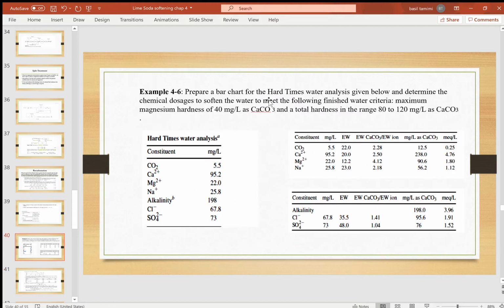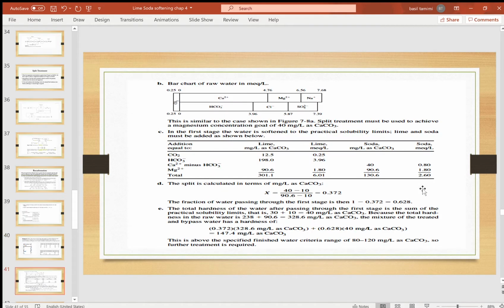the alkalinity and the calcium, let's say we have 238, we have an alkalinity of 198, which means I will have the difference between the two. I will have 40 milligram per liter as CaCO3 of calcium not covered by the natural alkalinity of water, which is this part. So this 40 milligram per liter of calcium not covered with the alkalinity needs an external source of carbonate. That's why we are adding here 40 soda ash. This 40 is to cover the non-carbonate calcium here.